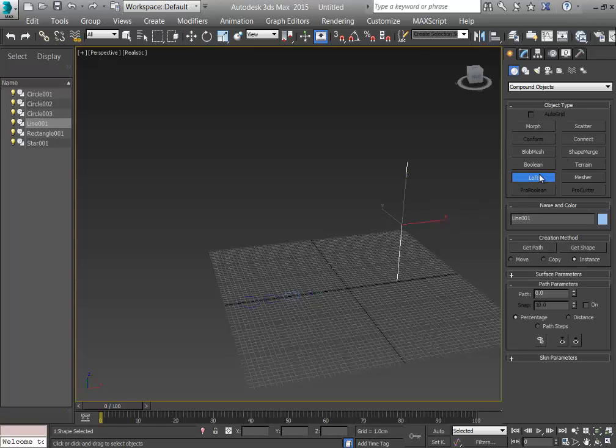See, I select a line, now the loft is enabled. So I click the loft tool now, and a set of new features arrives. Just a minute, I just want to check that the recording is still going on. Yeah, it does. That's nice. The loft tool helps you to merge two or more shapes onto one line structure.